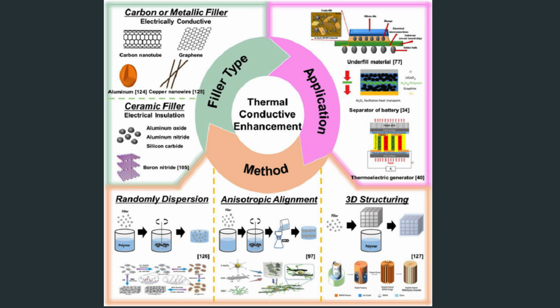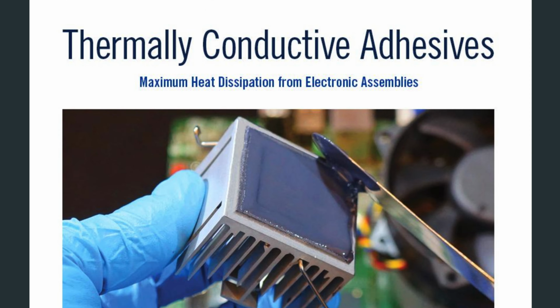In addition to filler composition, parameters such as particle size, morphology, aspect ratio, dispersion, and concentration significantly influence the thermal performance of adhesives. Hybrid filler systems that combine multiple materials and particle sizes have emerged as a promising strategy for achieving superior thermal conductivity through optimized conductive networks. Overall, advances in filler design, nanoscale materials, and hybrid composite architectures continue to drive the development of high-performance, thermally conductive adhesives that meet the growing thermal management demands of modern electronic devices and high-power technologies.